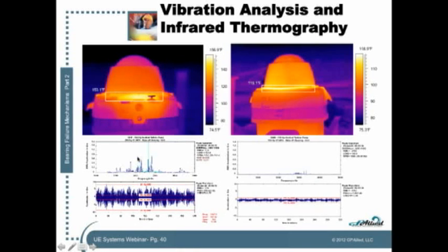When we collected the vibration data, you will see that the motor that had the thermal anomaly, basically the heat concentration, the hot spot, the vibration data definitely reflected that the upper race, pure vertical bearings don't have inner and outer race. They have a stationary race and a rotating race. And we found that it was the stationary race, the lower race, that had the defect. And it was a pretty significant defect. So these four pictures here probably are my favorite in terms of showing failure propagation.